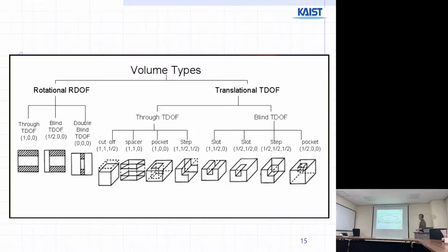So they have classified delta volume types. So rotational, it is related to the machining method, right? And translational, also milling machines. But there are through holes and also blind holes. So very simple classification of delta volumes. Once again, it is machining method dependent, right? Machining method. You remove material, delta volume material, from the stock.